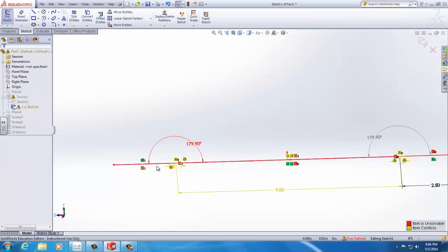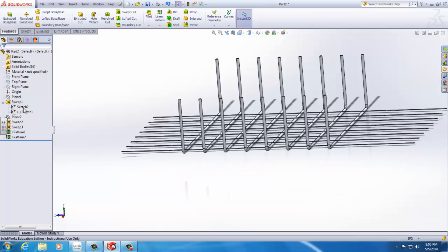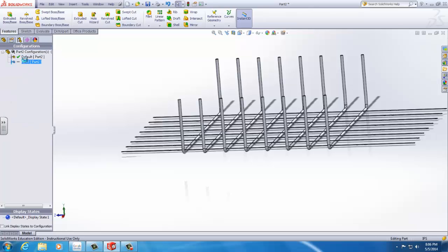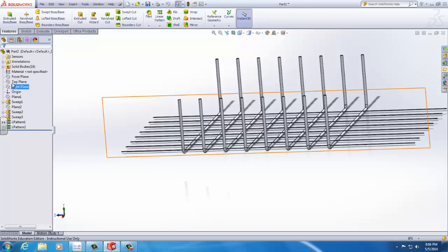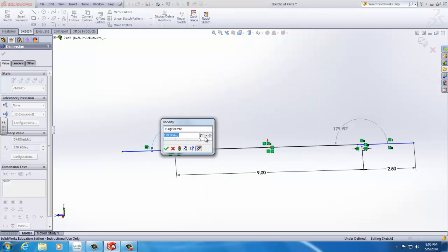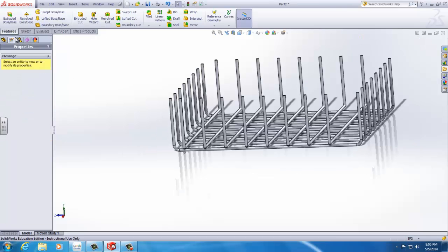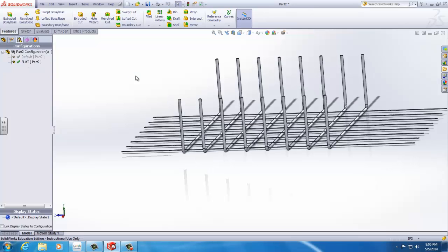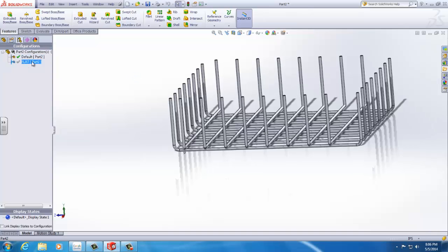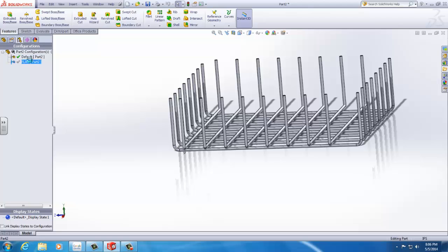Okay, so basically what we want to do is loft the surface, not just a regular loft. We want to go to Surfaces, Surface, and Loft. We select the first sketch, which is the front sketch, and then the top sketch. It doesn't matter which order you pick them in. That's our 90. And we're going to use guide curves, which is going to be basically that. Folds up, folds out, and so creates a section of the canoe.